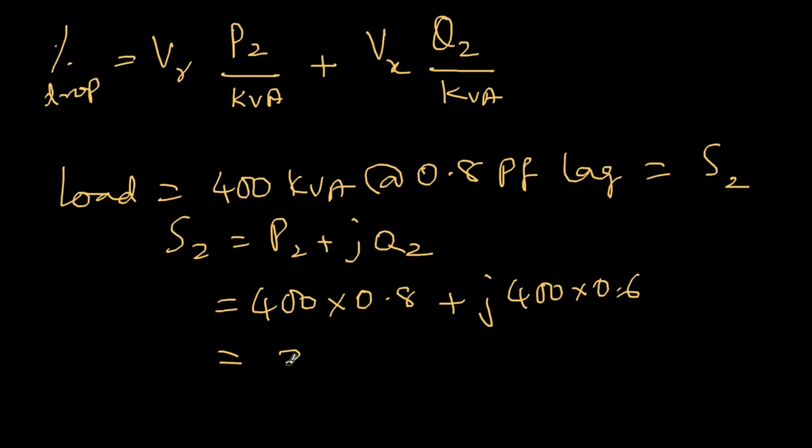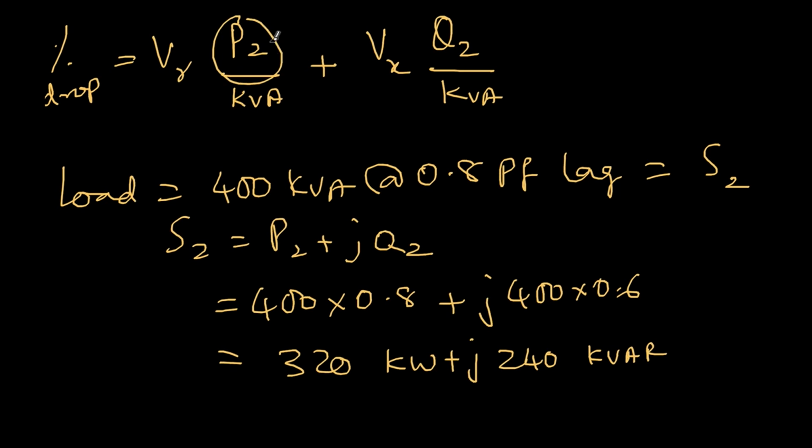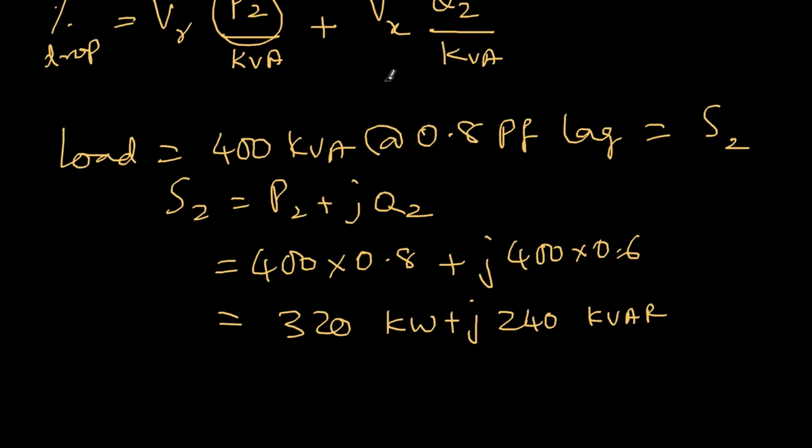So this is 320 kilowatts, because this is kVA, and this is 240 kVAR. Now that I know this, I can find the percentage drop.